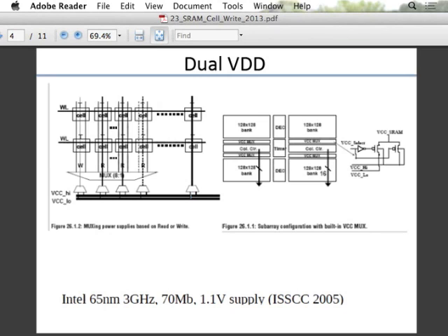Not a series of MOSes. There is one MOS whose body you have to change by 1 volt, and the threshold will change only by 100 millivolt. And body is again a capacitance, you have to charge and discharge that capacitance by that large voltage, so you are going to burn power for that. It is exactly less sensitive. The body influence is less. Here you can directly modulate the supply voltage because these cells don't draw too much current from that supply. So it's relatively straightforward to do this. So we can have a single mux and the output goes to all the columns. Correct.